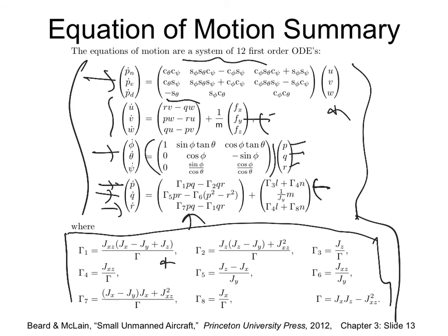So I will maybe show you that video of how it looks. That's it, equations of motion. Next class will be all aerodynamics stuff: how do we compute Fx, Fy, Fz, and moments L, M, N. Moments because of control surfaces, moments because of the propeller, and forces because of aerodynamics, drag, lift. When you move surfaces up and down, you will get rolling moments, yawing moments, pitching moments. I know it looks bad, but it is not as bad. It's all just writing equations peacefully.